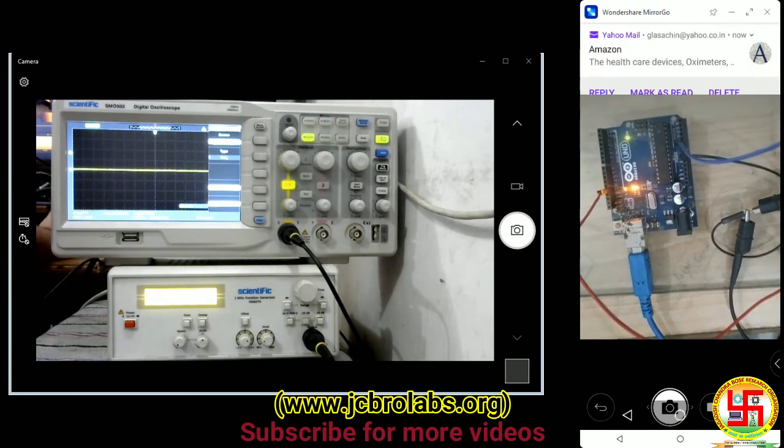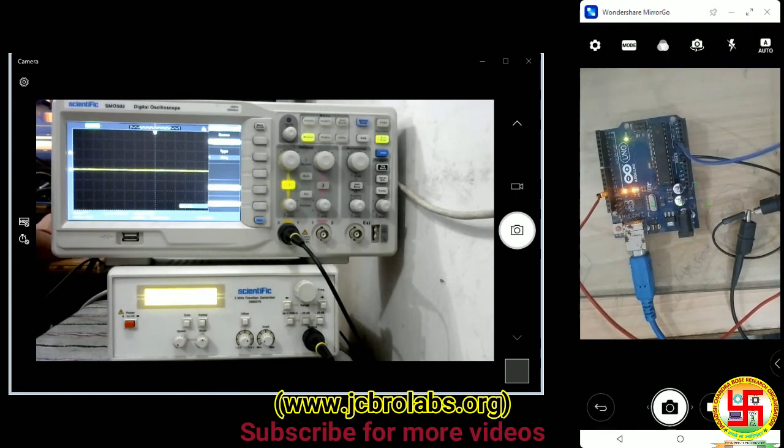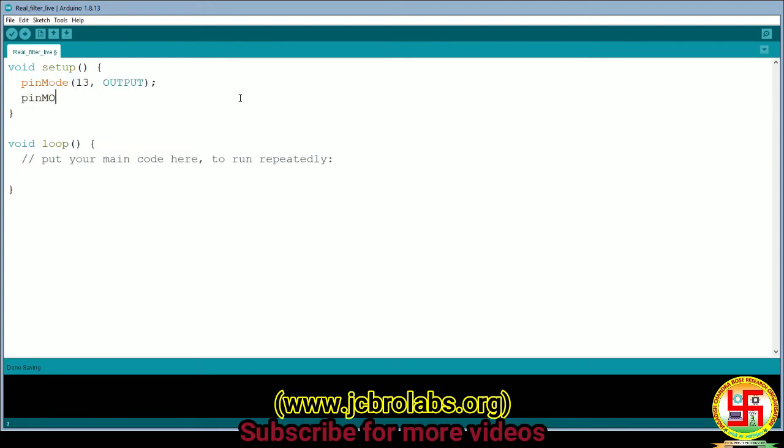Okay, now coming to writing the code. So we will come to the Arduino part. Here's the Arduino code. We have saved this Arduino sketch with the name filter live. Okay, and first of all we will set the pin mode of pin number 13 as output, and we'll set the pin mode of A0 as input.